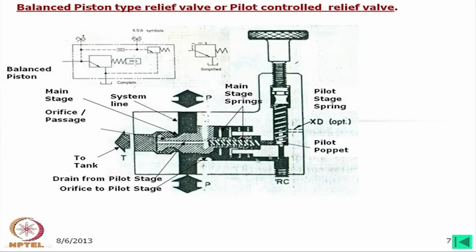If we develop the equations fully, from there we can understand how it is working, but for some valve definitely we will do that. But there is a difference between this balance type pilot operated pressure relief valve and the direct valve. There, direct pressure is opening the poppet; here, the differential pressure is opening this poppet.